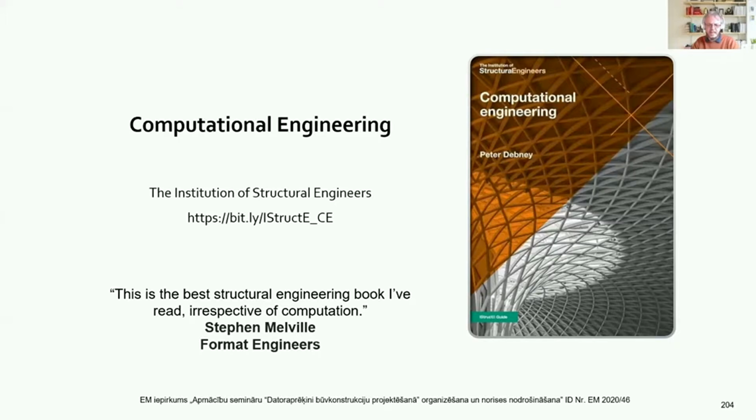There are some architectural level form finding programs for fabrics anyway. For example, a program called Easy gives you approximate answers, close enough for an architect. And a lot of people also these days are using Rhino Grasshopper models with the Kangaroo plugin, which gives you force density within the model. So yeah, there are various answers. Obviously, speak to me about GSA, and we can arrange for you to have a look at that.